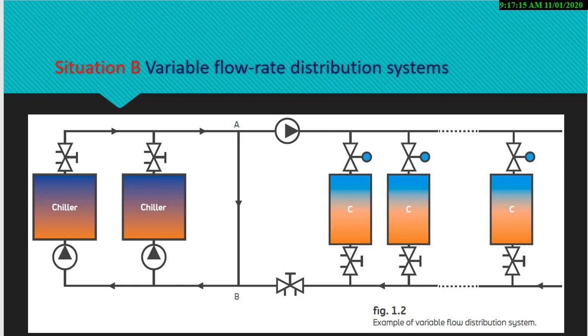DPCVs set the differential pressure to the desired level. This level should be adequate to obtain the design flow rate in the furthest pipes while not exceeding the maximum value associated with the valve actuator combination, based on the maximum force of the actuator itself.